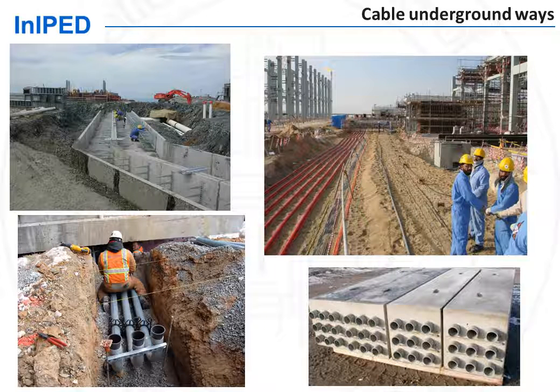Underground cable systems include direct buried trenches or concrete trenches. Direct buried trenches are used outside paved areas, since there is no paving, so access to the cable is possible. When there is a paving, cables have to be run inside a concrete cable trench with a removable cover.